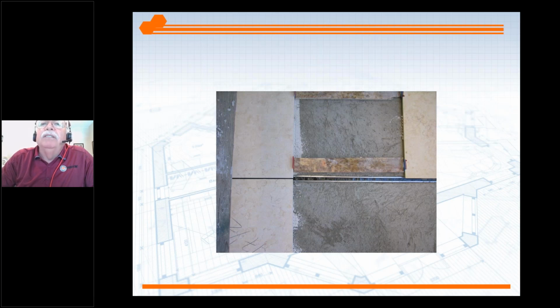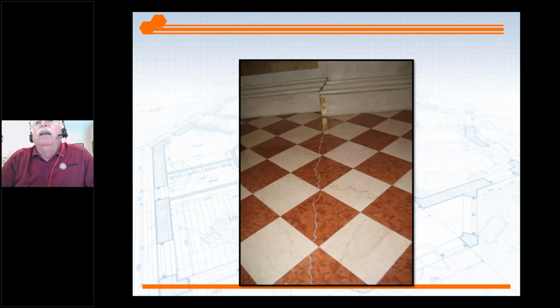The engineer knows how much this building is going to move, and the tile contractor is making it smaller. You need to use the exact same size as what's on the building itself, because that's the allowable movement on that structure. Even diagonal, it's still going straight across those diagonals. Tells me there's some type of movement joint underneath that tile. Now, of course, if your client has enough money and room and thinks of these floors as disposable, they can come back in and fill this back.